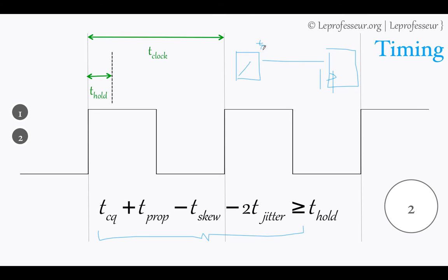Your signal is propagating and it should not change in this whole window. It should be stable, and then change if it is changing at all. If it is changing in between, then the job here is to increase the delay. And how can you increase it? Simply insert buffers in the path.